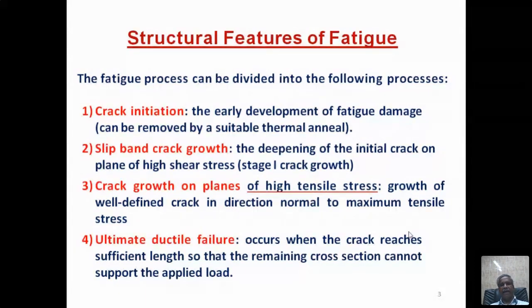This fatigue process consists of 4 stages. The first one is fatigue crack initiation, which is normally the early development of fatigue damage. But this crack initiation can be detected by non-destructive testing methods, because now we have very excellent non-destructive testing techniques available. Without damaging the component, you can detect any defect, any nucleus of defect, using ultrasonic testing, radiographic testing, even computed tomography. So many techniques have come now to see that.